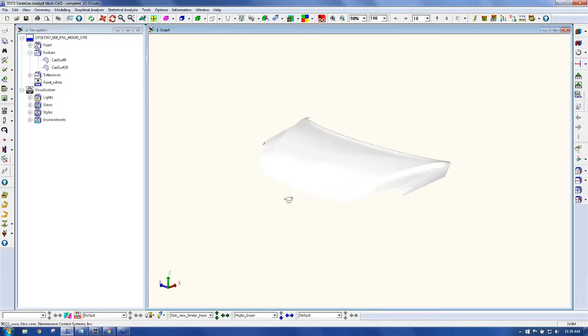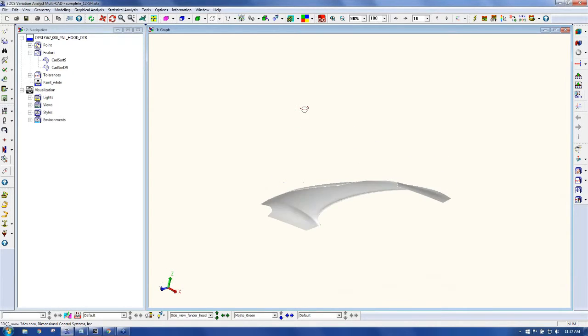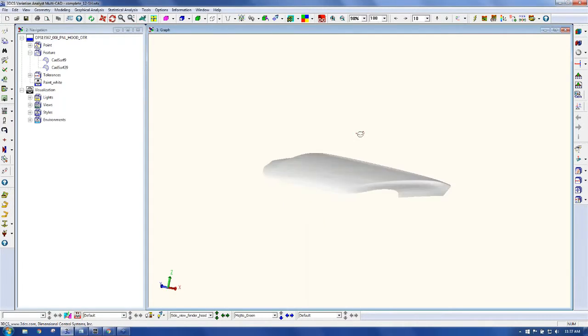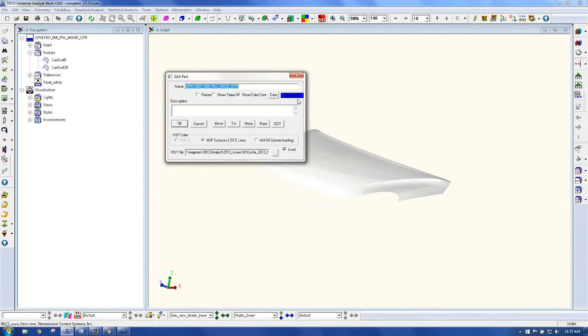So with this piece here, when we go into VRED and Showcase specifically, these are the Autodesk products, correct. It's going to get its color. Right now I have this hood painted white, but it's actually going to get its exported color from the actual part color. So it's not the color that you actually see in your model right now. It would be the default color for this part. So this part will actually import into VRED and Showcase as a blue hood, not a white hood.